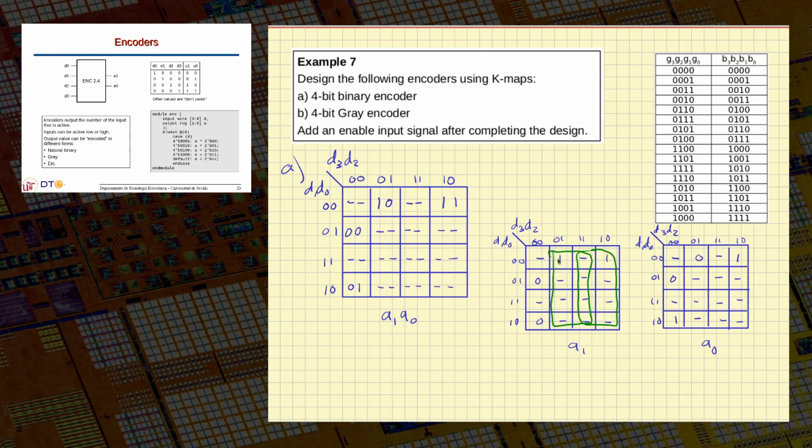For example, this one is a prime implicant as well. Okay, we may consider this, but this is of a smaller order than the ones we already have. And we don't really need to cover the don't cares. So it's not necessary to consider more prime implicants. This is the remaining one that we may consider, but we see in advance that it's not necessary. And for the other one, this is a prime implicant as well.